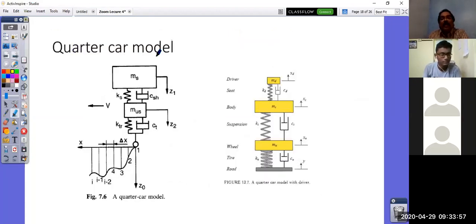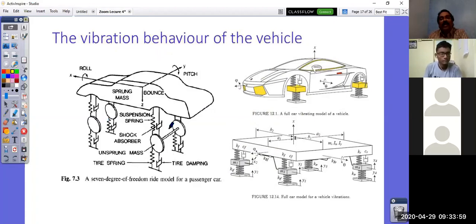So we do not necessarily require a huge, complex degree of freedom model for some qualitative assessment of your vehicle ride. There are some important motions like bounce, pitch, and roll of your sprung mass as a whole. If you know the sprung mass critical resonant frequencies, those data are sufficient to design your suspension in order to have limited amplitude of those vibrations.